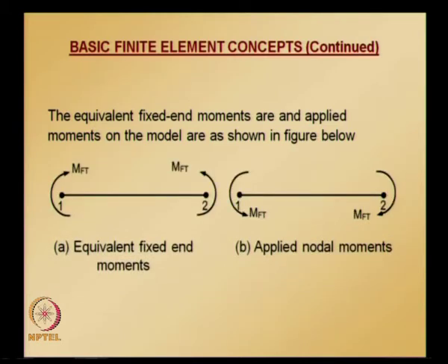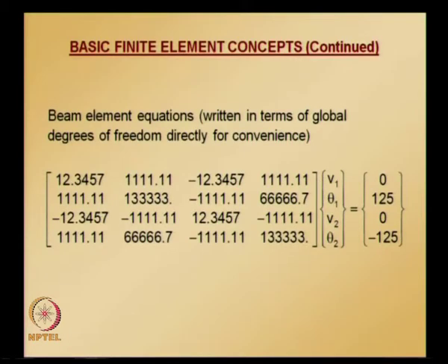Here the equivalence between the fixed end moments and the equivalent nodal vector is shown. Once we get the fixed end moment MFT, we need to reverse the sign, and we get the equivalent nodal forces, and then we can write the element equations for the beam element. Please note that for the beam element, the degrees of freedom are V1, theta 1, V2, theta 2.